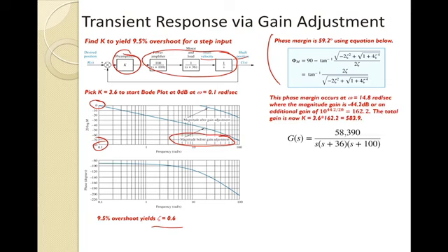So this phase margin, if I look for that, will occur at about 14.8 radians per second. So here's 10, 20, so somewhere about halfway in between here is where that frequency is. And again, if I were to go up right here, you'll see that's about minus 44 dB. So here's 40 and 50, right in the middle of that as shown there.